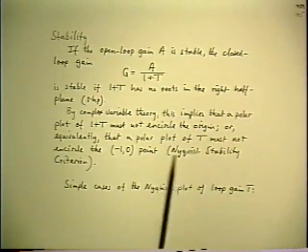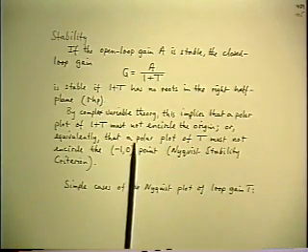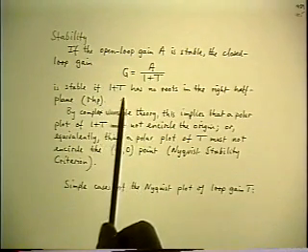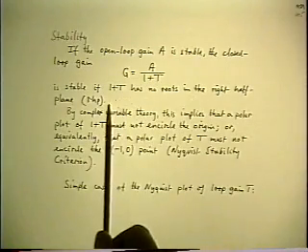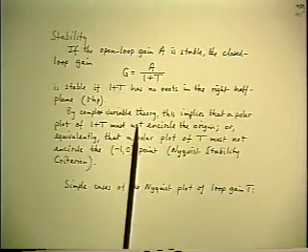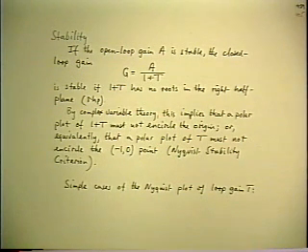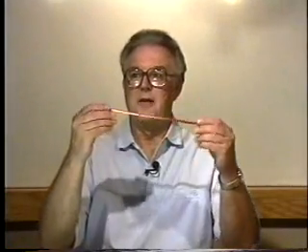Now, Nyquist's name is usually associated with the stability criterion, and what Nyquist did was he translated that condition, F has no roots in the right half plane, into an equivalent condition that says if you make a polar plot of F, a polar plot means that you draw a graph of F as a function of frequency using the length of the phasor representing its magnitude and its angle being the angle of F. And you trace out this contour as a function of frequency, and you get a closed contour as a result.